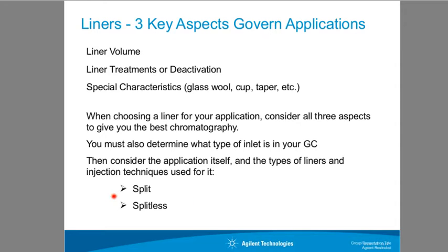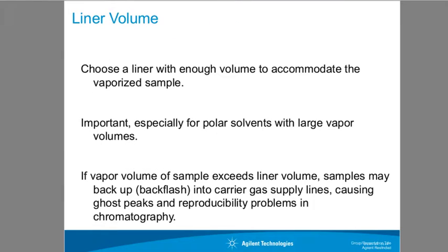If you're starting out with a new method, new application, I would highly recommend starting in split mode. You may end up changing liners if you go down to splitless, which is fine. But if you're doing a split injection, you can't flip-flop different styles of liners under the same conditions and expect to get exactly the same results, because the glass wool, the shapes, and the sizes of the liners do change a little bit, and that's all going to have an influence on your sample and how it's treated through the inlet.